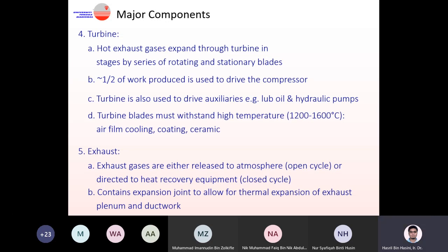For the combined cycle, yes, we use that for the intermediate load, or in some cases maybe for the base load. That is for the combined cycle. We don't use open cycle for intermediate load. We use open cycle only for the peaking load.